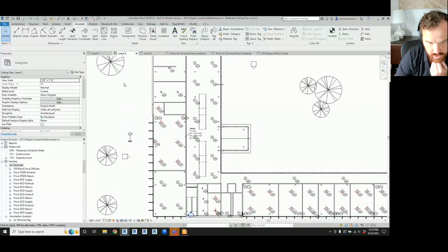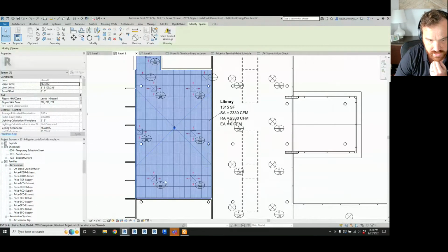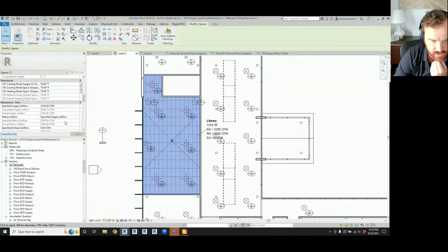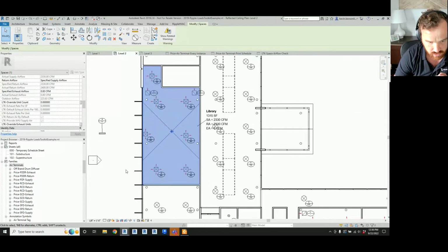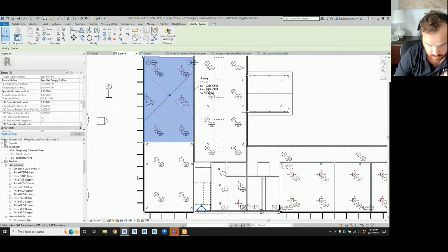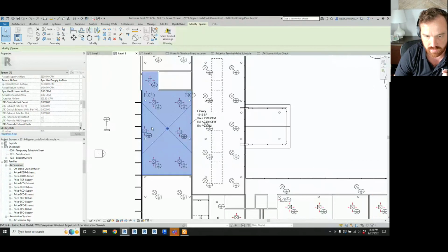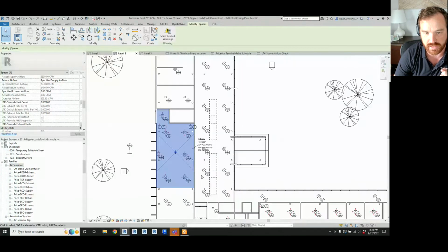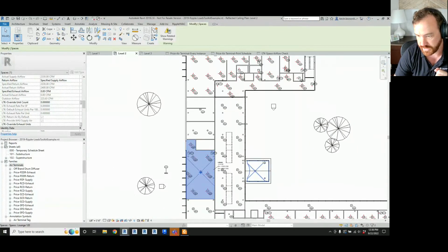As I said, the most important groundwork to get laid out is to get your spaces in and to get your CFMs assigned to your spaces. Once you go from there, it should just be clicking through, checking reasonableness and moving on. So get all these out of the way, and focus your time on those complex spaces that need more attention.